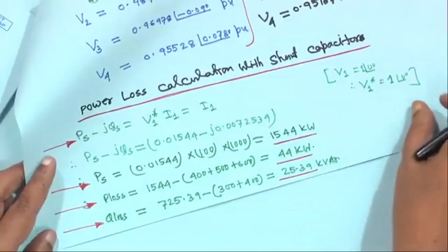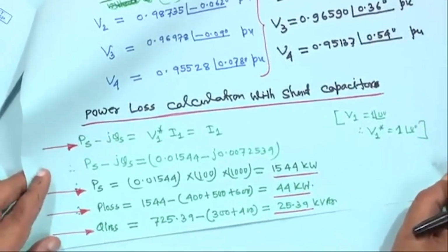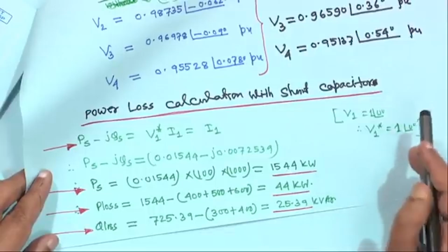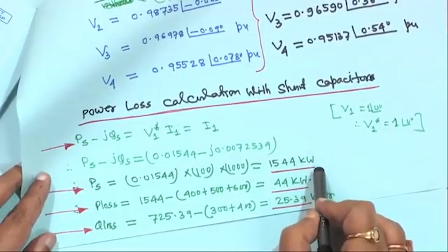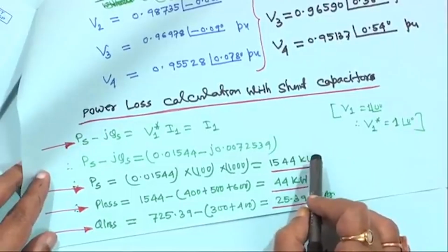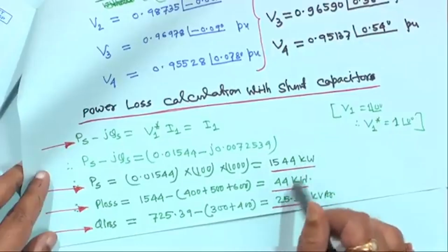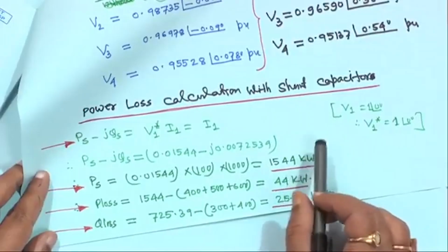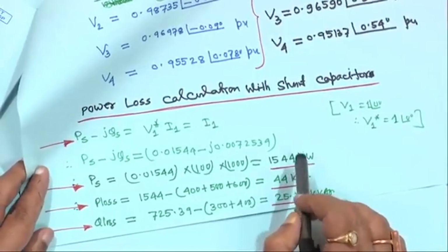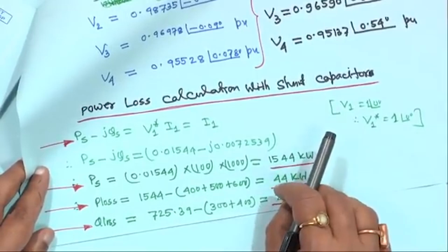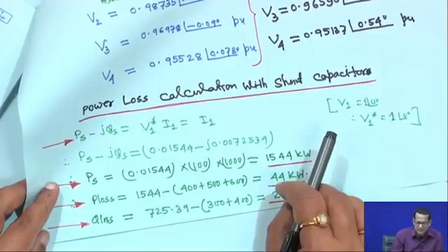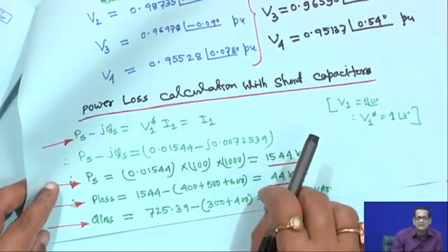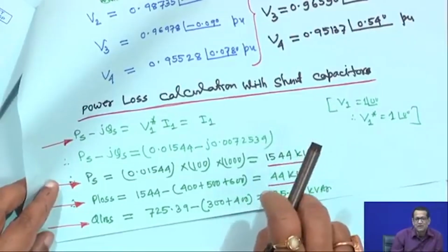If you go to any substation anywhere, although it may be on the 33 kV side or 66 kV side, in the distribution system also you will find that utilities all over the world are putting shunt capacitors, at least 2, 3, 4 shunt capacitors. For that they try to find the best location. Say you have a 120 node distribution network, or even a larger one; you cannot arbitrarily put a shunt capacitor, then instead of gaining you will be the loser, loss may increase also, if you do not put it in an optimal place.